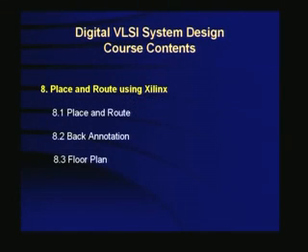And once you do it, you go back and see the back annotation. When you make that placing and routing, you may make some minor changes, and when you back annotate, you go back and verify whether your design is still what you wanted. So that is called back annotation. And then you have what is known as a floor plan, which shows which units of the FPGA will be connected in what way.